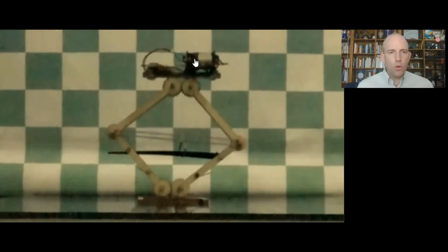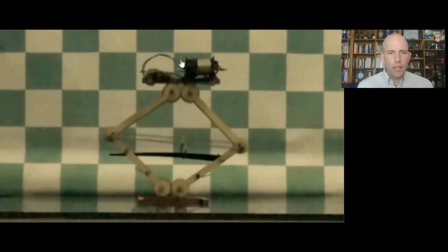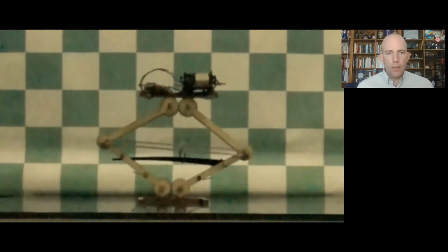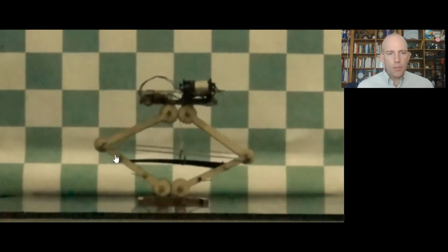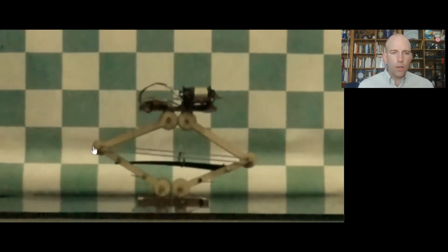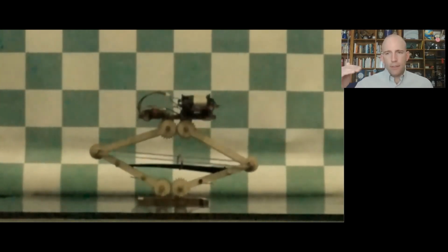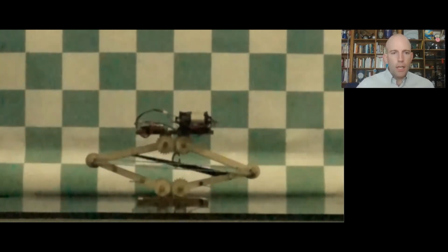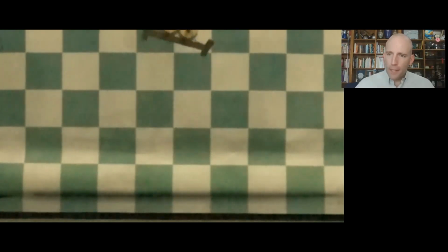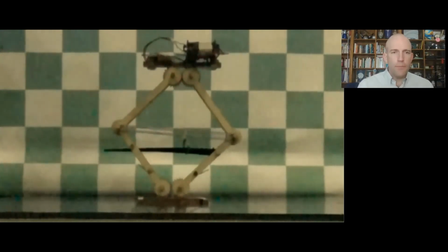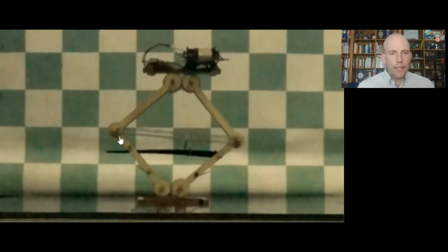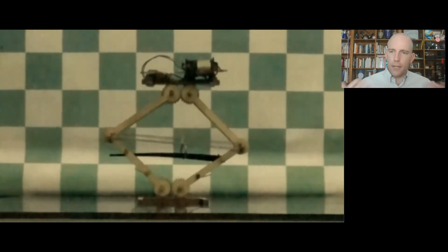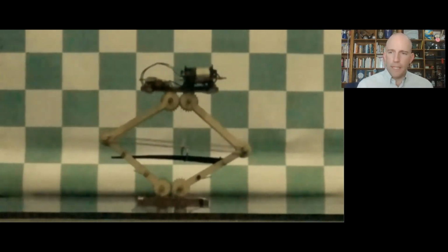What's happening is there's a motor up here, it has a drum, it's reeling in this rope. Then that rope is tied to this ring that can slide along this lever, and the lever can also slide along this shaft in one of the legs. Eventually, as it gets very near the bottom, that lever can slip off and the whole robot will jump up into the air. So let's watch that one more time. And I want you to think, specifically about this release mechanism, where could we lose energy? How could we be dissipating energy?